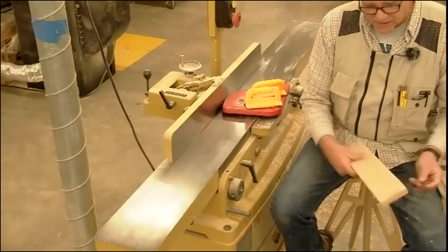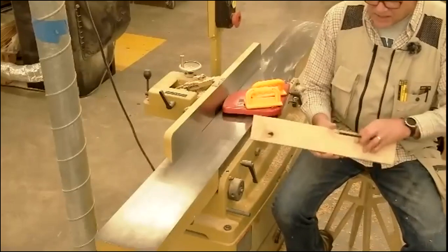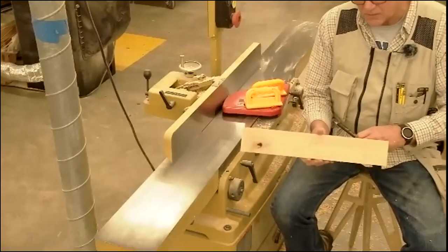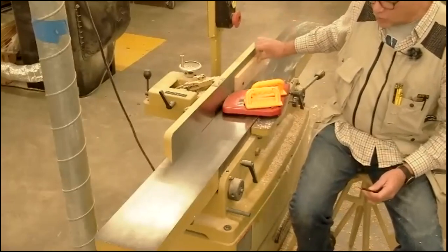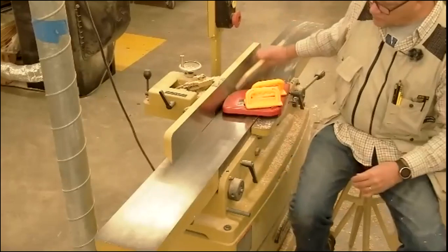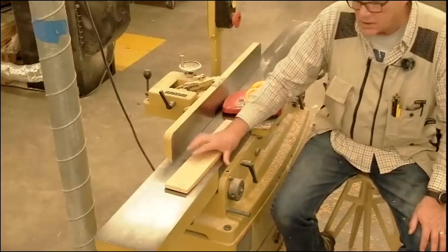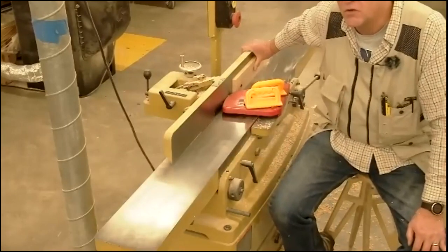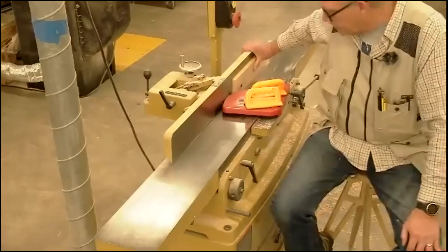So the thing that having both faces flat and parallel after coming off the planer does is help when you go to joint the edge of the board, prior to going to the table saw, okay? So you joint one face, plane the opposite face, come back, joint one edge, so that when you go to the table saw, you can place that long jointed edge against the fence, okay?